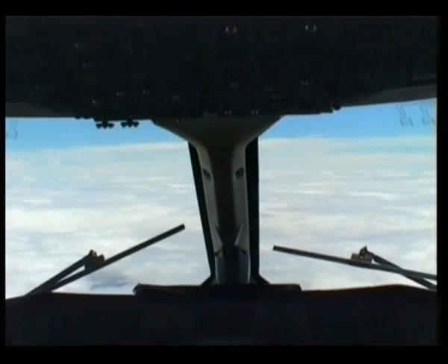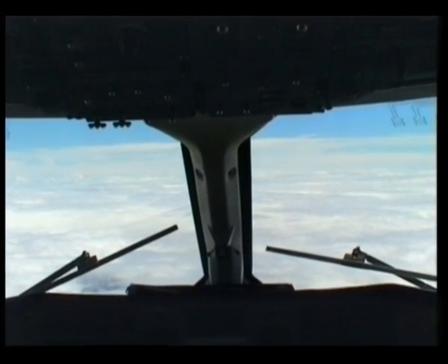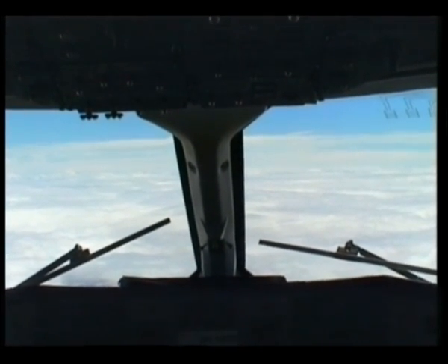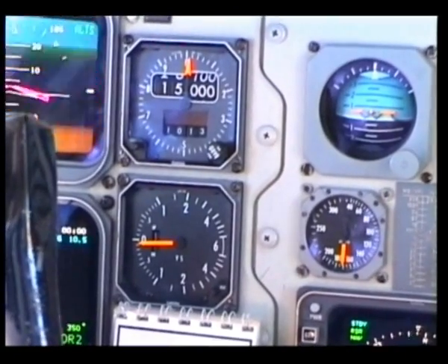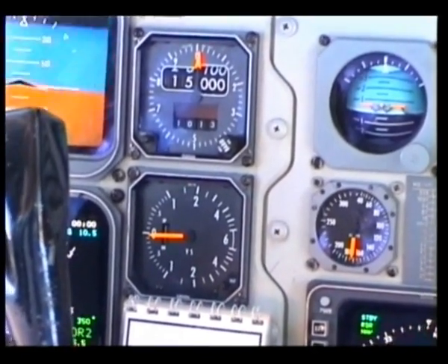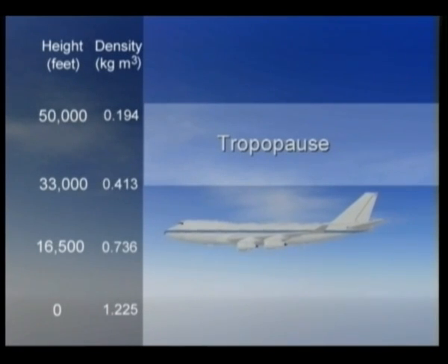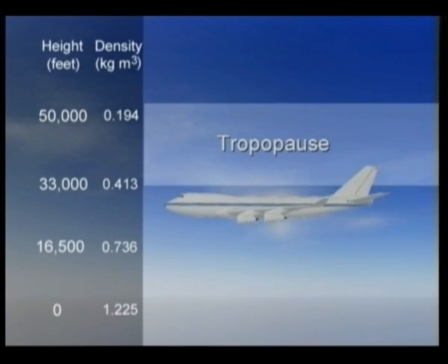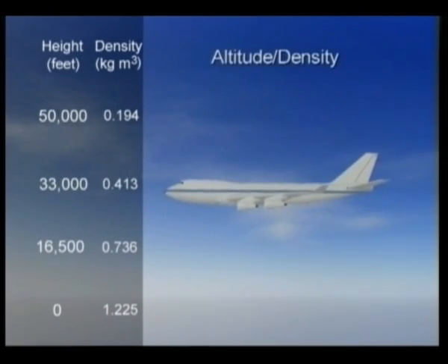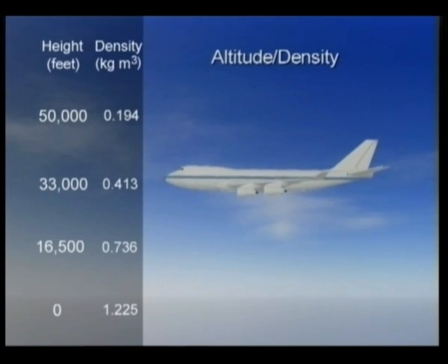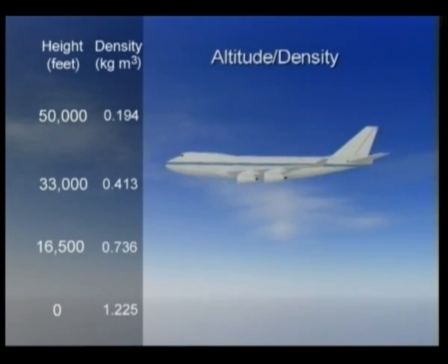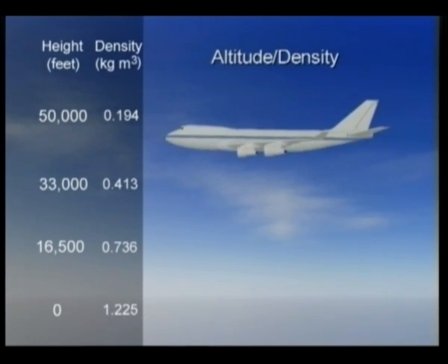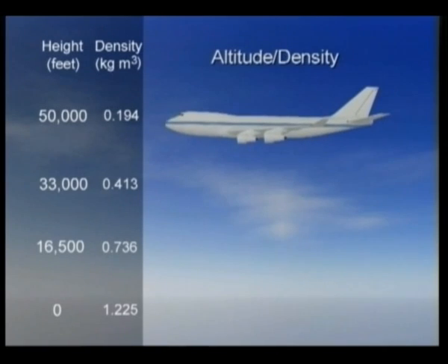The higher we go, the less dense the air, and, since gas turbine engines operating in rarefied air suffer from respiration problems, we should not fly 1 foot higher than is necessary. For long-distance travel, the tropopause, the boundary between the troposphere and the stratosphere, is where conditions are optimal, where the highest density consistent with the search for low outside temperatures is found. The relationship between temperature, density and altitude may be illustrated by the following example.